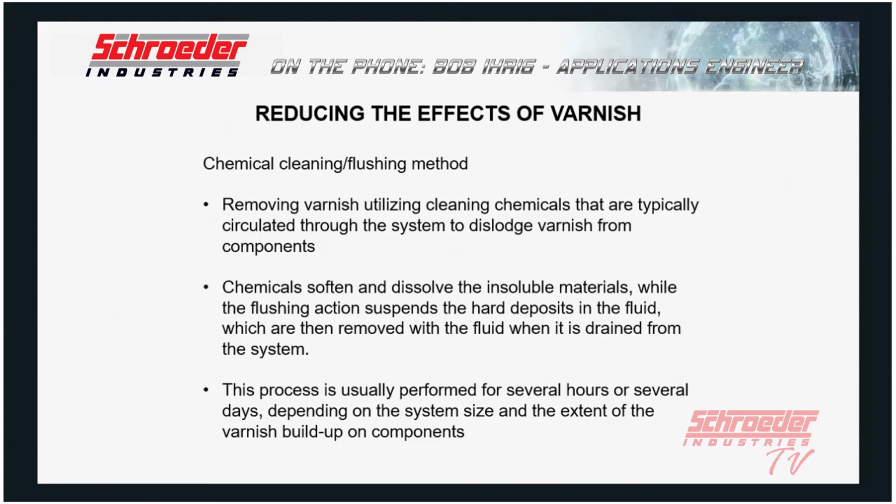This is probably the least practical way of dealing with existing varnish, which would be chemical cleaning and flushing, for obvious reasons. The chemical typically used to do this is a variation of a fluid or an additive, which is basically a solvent, and it's added to the contaminated fluid.